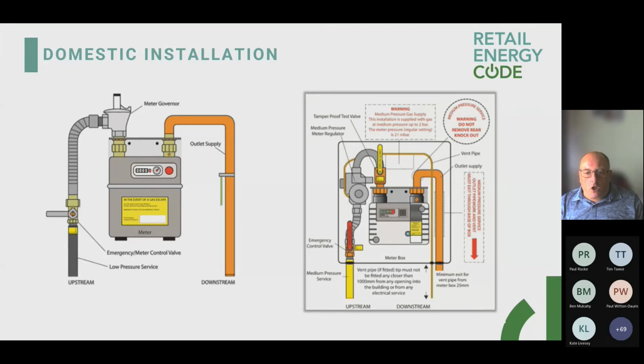customer. So we have to put a different type of regulator on it, and this is what they call a 2-stage regulator. You'll notice that the colour of the handle on the emergency control valve is different, so that enables our operatives to identify that it's a medium pressure rig because it's got an orange stroke red handle on it.